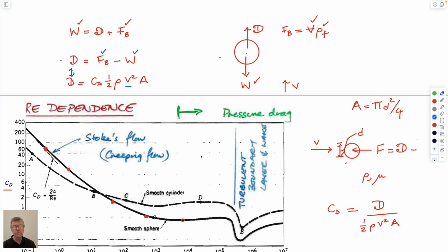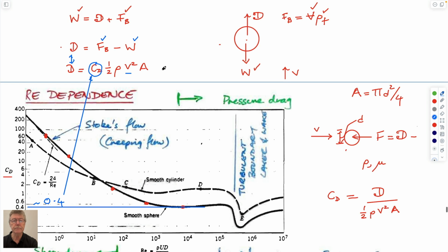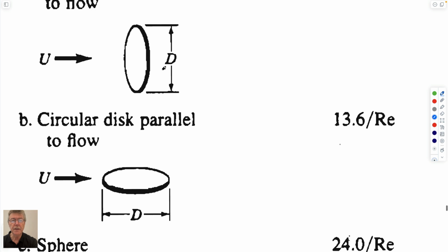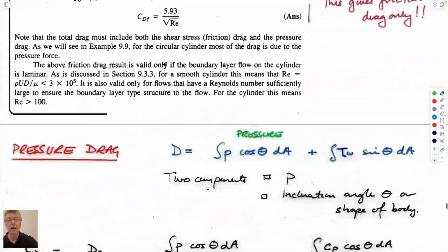If you know you're turbulent, you know that the coefficient of drag is something like about 0.4. And so if you know what this is, 0.4, then the only term you have to calculate is the velocity. So you need to get that. And so you can solve for terminal velocity. This turns out to be 200 miles an hour or something like that if you do this for air. So I guess that's kind of impromptu. So that's where we ultimately will go.